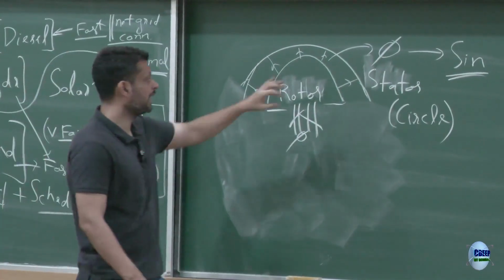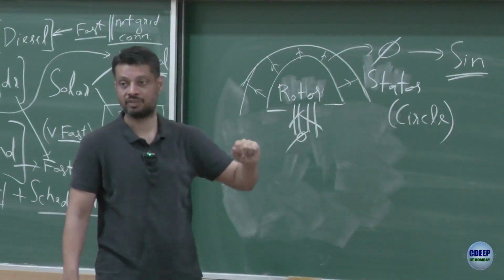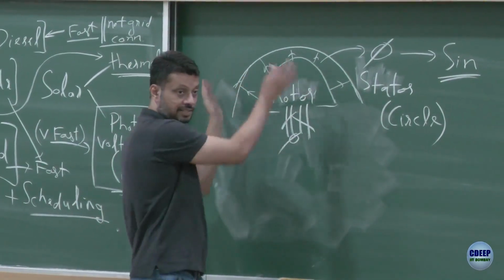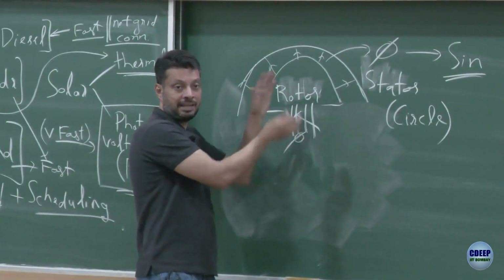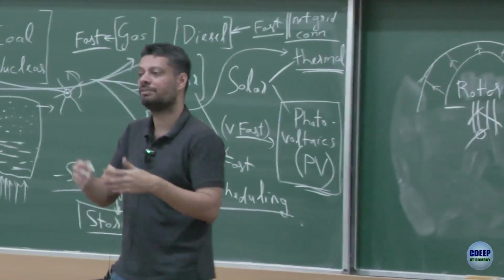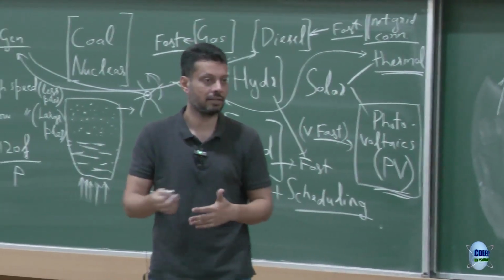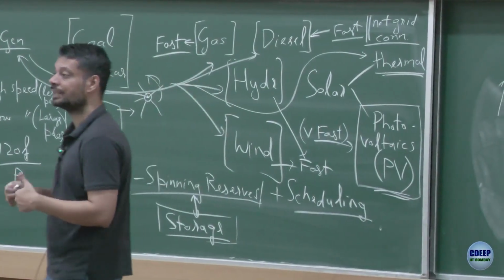Is that okay? Earlier you had a constant flux density, so if you rotate it, you get that kind of wave shape. Now you have a sinusoidal flux density. So if you rotate it, you do E equals N d phi by dt, and the derivative of that sinusoid or cosine would eventually lead you to a sine or a cosine. So the shape of the voltage induced is now going to be sinusoidal.